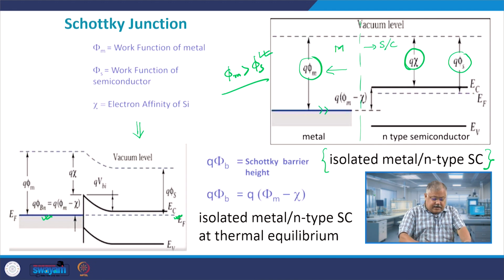You can see that the energy band diagram near the interface has gone up. It is almost like giving a positive bias on the n side. Without giving a bias, you can understand this point: if you give a bias, the whole band will shift to the bottom because it is minus q times V. As it shifts to the bottom, near the edge, it still remains at the top.